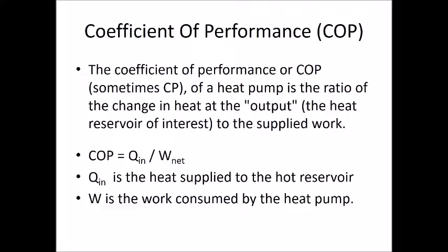So this is an expression that you will feel familiar with, because it looks very similar to how you might calculate efficiency. So this is the ratio of the change in heat at the output side versus the supplied work. Okay, so if we were looking at a Carnot efficiency for a power station, it would be work versus heat. And I always say to you, divide by the thing that costs you money. So in the case of a power station, the fuel is going to cost me money, so I divide by that. But in the case of a refrigeration process, let's assume that it's electricity that we're buying in order to get our refrigeration effect. So that's the input to the process.